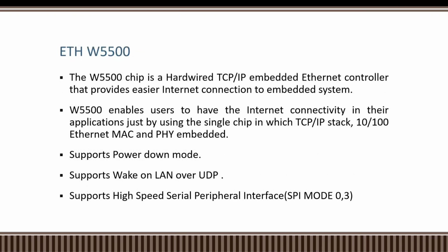Ethernet, ETH-W5500. The W5500 chip is a hardwired TCP/IP embedded Ethernet controller that provides easier internet connection to embedded systems. Here, TCP stands for Transmission Control Protocol and IP stands for Internet Protocol. It enables users to have internet connectivity in their applications by using a single chip in which the TCP/IP stack, 10/100 Ethernet MAC and PHY are embedded.